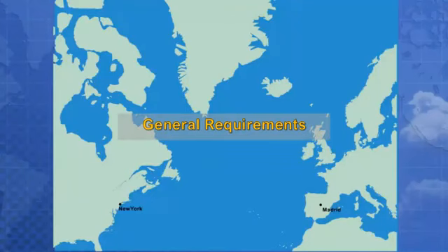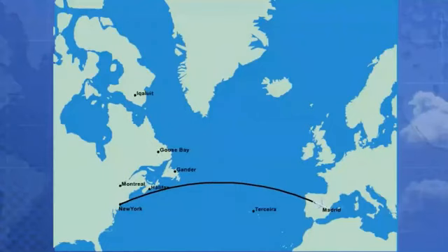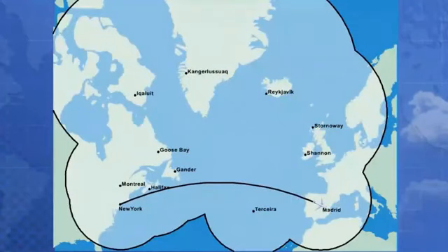General requirements. Basic fundamental ETOPS concept can be described as follows. For a desired route, an allowable ETOPS area of operation is determined by locating adequate airports that can be utilized as en route diversion airports. Engine inoperative still air diversion distance circles are drawn around these airports such that the planned route of flight is enclosed within the circles.